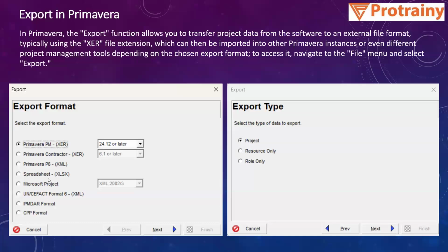And basically, this Primavera XML file is used in various software, like Synchro 4D, if you have heard of it. Synchro 4D uses the Primavera XML file, so you can import that file into Synchro 4D, where you also have your Navisworks model of the plant, and you can integrate the components of the model with the schedule.